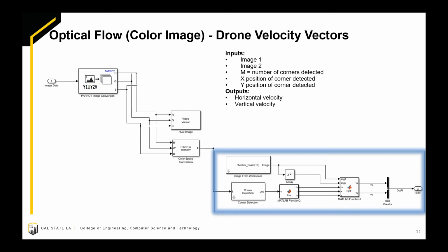Optical flow is the distribution of apparent motion of brightness patterns within an image, the motion of the image pixels compared to neighboring pixels. And the Lucas-Kanade method solves for these apparent velocities by using the least squares method. The MATLAB function block in the orange is a script that incorporates the Lucas-Kanade method. Errors using optical flow with this method occur with low contrast and poor resolution of the images and large motions captured between consecutive frames. With the increase in error proportional to the frame rate, the time between consecutive images must be small to get feasible velocities. The corner detection values also help the drone focus on edges of the path during turns.